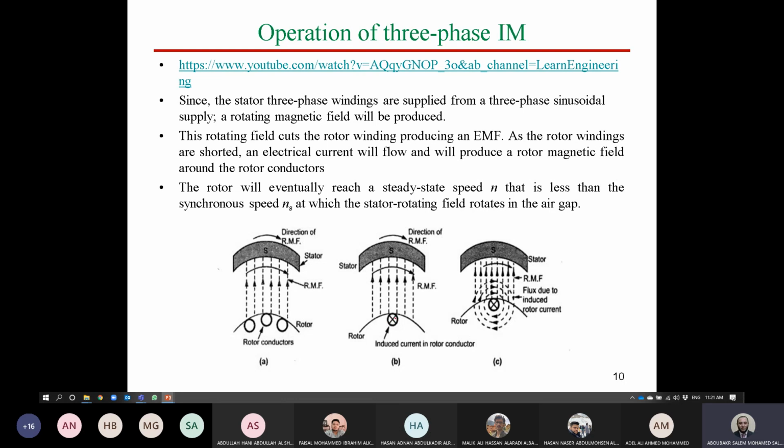But when we have current, the armature reaction, when you have current moving in the conductor, it is going to make flux around this conductor. And this flux will have a component like that, guys, in this direction if the current is going into the page like that. Okay.